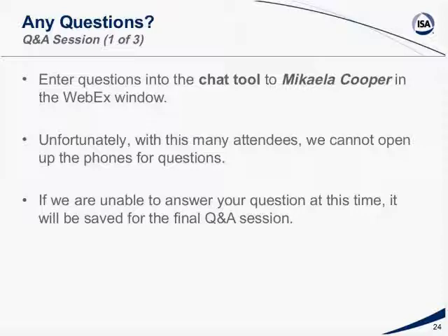Absolutely. Batch processes are fairly unique in this regard because you'll have the process running and you'll go from one recipe step to another. And yes, you do want to alert the operator, and it needs to be a unique alert letting him know that this sequence is ended, it's time to start the next sequence. So when the operator hears it or sees it, they know it's not an abnormal process alarm. It's just normal sequencing within the batch process.